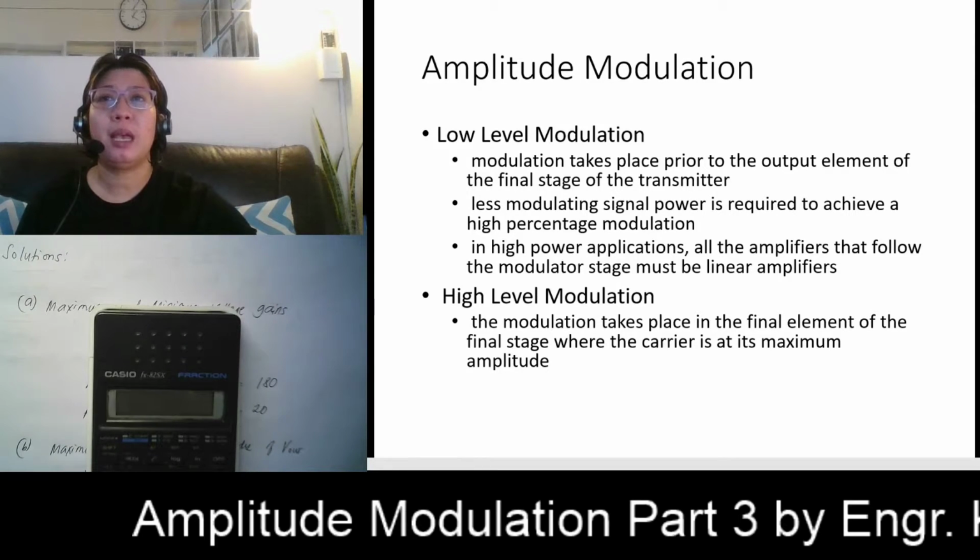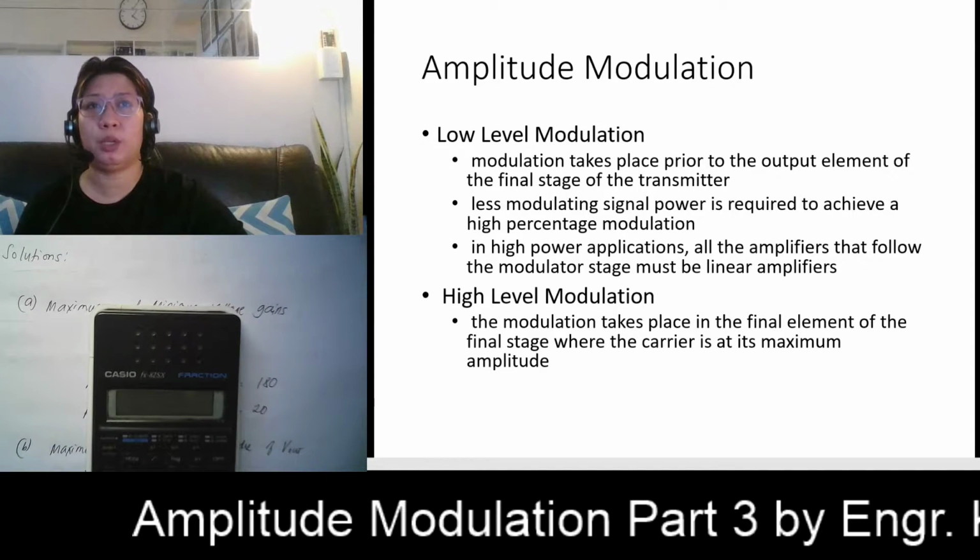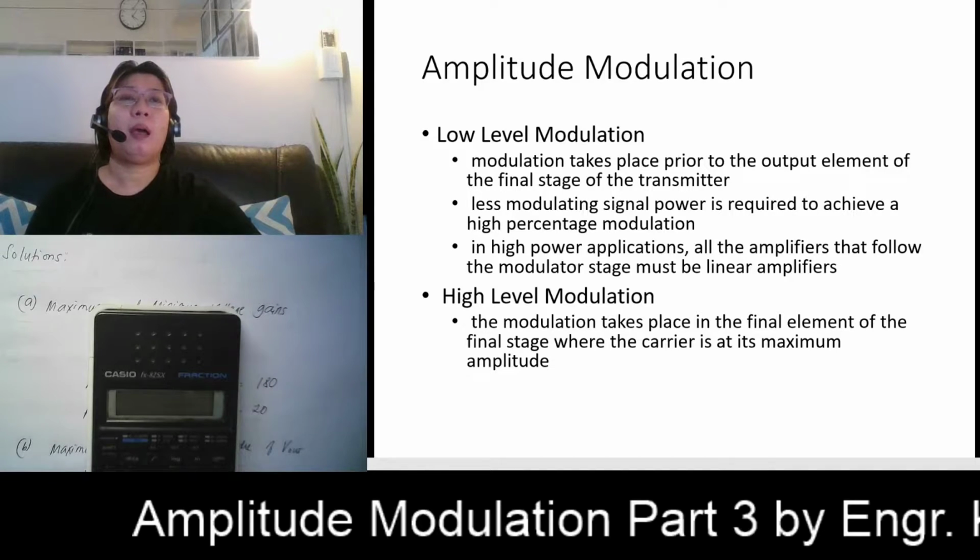This is extremely inefficient, because it requires a much higher amplitude modulating signal to achieve a reasonable percentage modulation. Usually, the final modulating signal amplifier must supply all the sideband power, and that sideband power is usually 33% of the total transmit power.